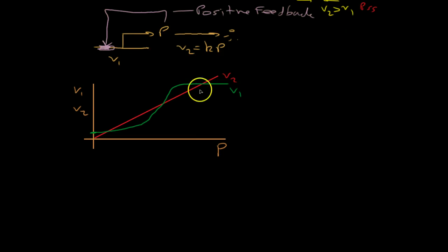Okay. So that one is V1. And you can see probably immediately that there are actually 3 intersection points. These points mark when V1 equals V2. These are 3 steady state points. So this system has 3 possible steady states at a given set of parameters. So let's look at the stability, say, of this high state. Let me drop down a line. So this is the steady state. That's the steady state level of P.